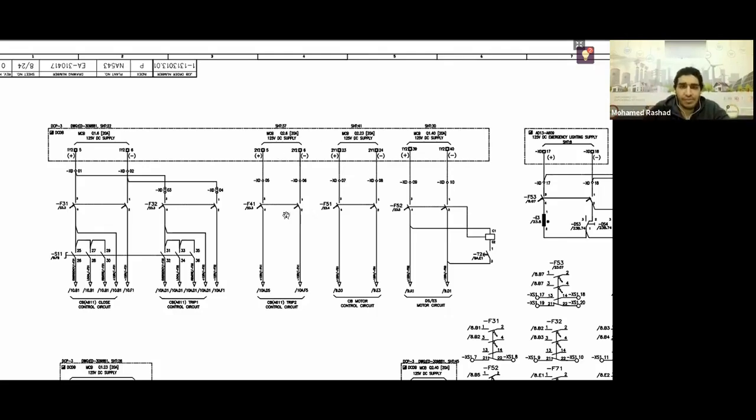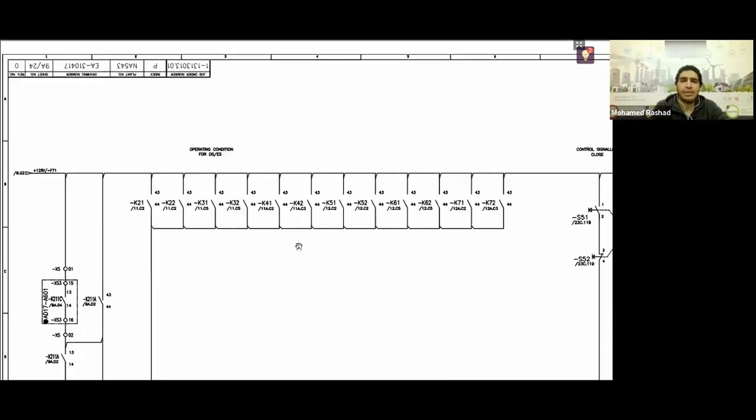The trip circuit comes to you with positive and negative directly, whereas this one comes with positive and negative passing through an emergency local remote. So you would expect that one of them allows you to open or close in an emergency or local remote, while the other is dedicated specifically for tripping only. You might also find some interaction between them, which you will see now together.